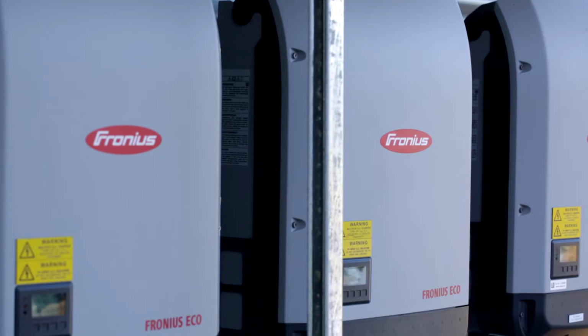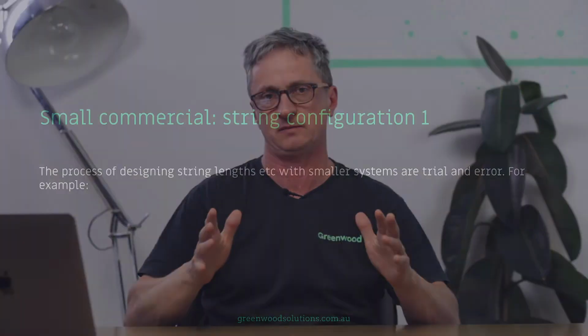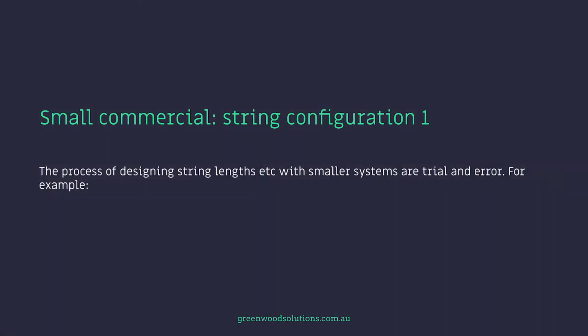In this example, we're looking at 3 Fronius Eco 27 inverters. We're using 445 watt panels, and we want to design a system that takes into consideration the string configurations and just comes in under that 100 kilowatt limit. Now, the process of designing string lengths, etc. with small systems is trial and error.